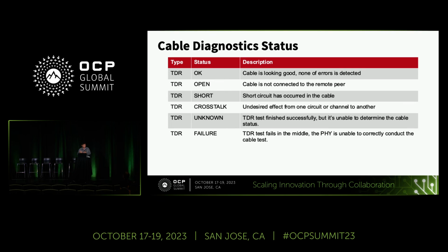You send some kind of pseudo random signal, and you know what you sent, so when it is received you know whether it's the same as what you sent. And TDR is basically just using the reflection of the signal to determine, for example, the cable length, because by physics the signal travels at a certain speed for different types of cable.